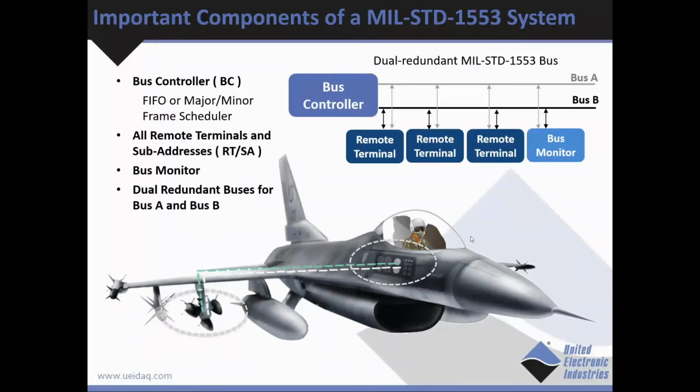A FIFO-based bus controller is excellent at targeted testing of many RTs and SAs. But when you need to send commands to many RTSAs at different frequencies to emulate a real aircraft, the major-minor frame scheduler is the solution. The bus monitor is an option to be used or not, and simply allows you to view or record any or all traffic on the 1553 bus. It cannot interfere with this traffic in any way.